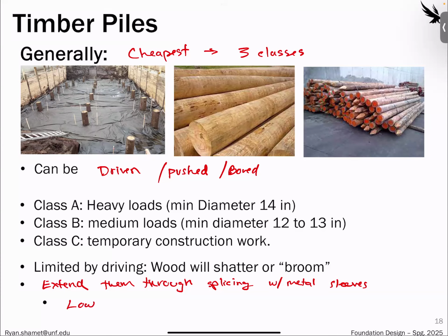Again, most of the time it's going to be low structural load or lots of piles, so you disperse. If you do have a lot of structural loads like this, then you would just have them close together and almost serve as micro piles.